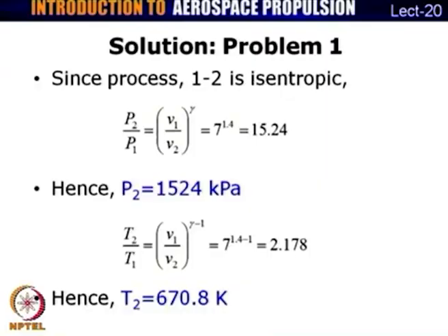And here I think I missed mentioning that gamma, which is being used here, is the ratio of specific heats. In most of these ideal cycle analyses, we will be assuming that air is the working medium, and for air the ratio of specific heats, gamma, is equal to 1.4. So, we will be assuming gamma as 1.4 in this as well as the remaining problems.